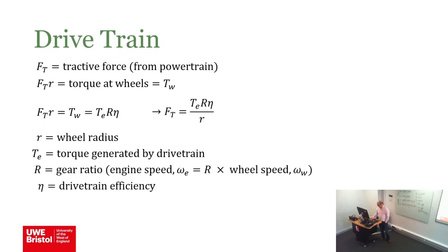And like I said, through a certain efficiency. So FT is TE R mu over r, so if you know big R and you know little r, and the efficiency, you can work out the torque required by the engine to give you that tractive force.